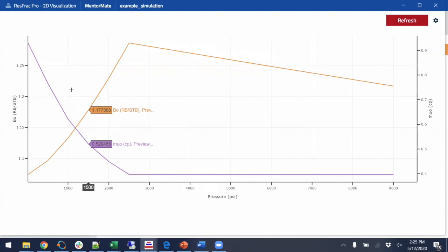This is the same visualization tool that we have elsewhere. And this is useful. Note that it's not just plotting the numbers in the table. For example, this is the bubble point pressure that's been inputted. Rather than showing the saturated BO from the table, it's finding, hey, we're at that saturation point, and then this is the behavior of BO as pressure goes up beyond that.